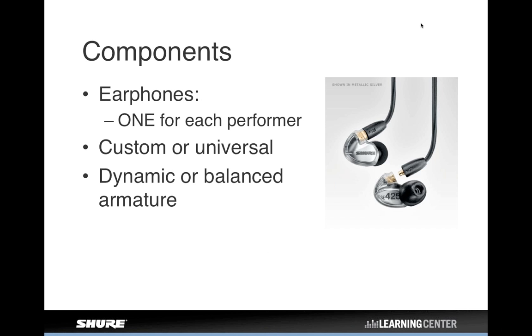So that means that you're not going to use your iPod earbuds to monitor on stage for a professional application, because those things don't really isolate at all. They just kind of sit in your ear and make a little bit of sound. So you really can't use those. You really have to get one of these professional type of in-ear earphones. There are kind of 2 basic types: custom earphones that are specifically made just to fit in your ear, right, with a custom mold, or universal type of earphones, which is what all the Shure SE earphones that you might get in conjunction with one of our personal monitor systems.